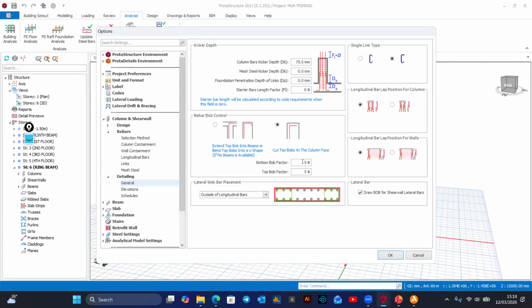So it is from here that now you can even judge based on the size of your structure. You can tell that this structure maybe is too big, it's having heavy loading. I'm going to use maybe T20 bars. So if it is T20, you can determine the size of that hook, how it will be. It will be 5 times 20.